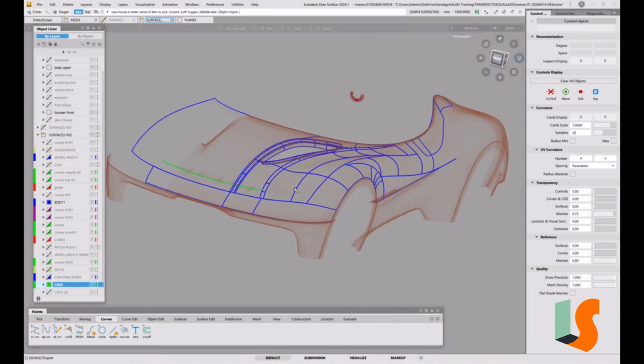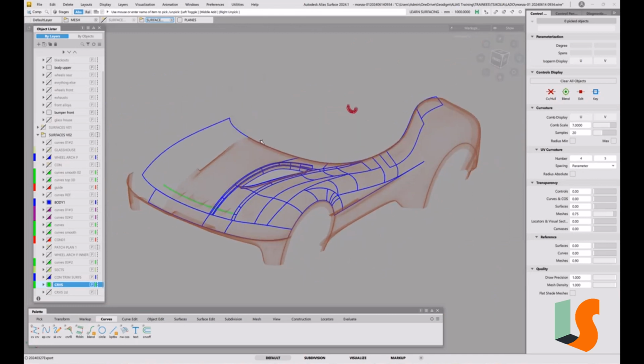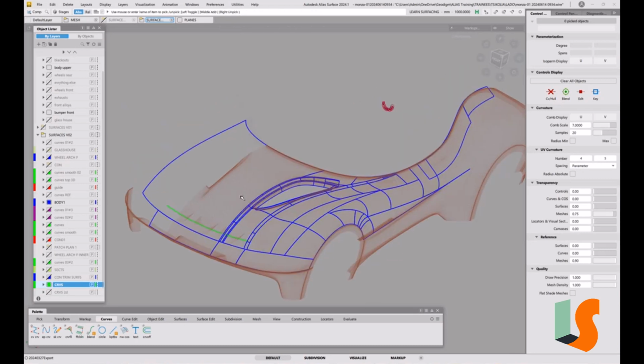Now, before we do that, we've built surfaces across the center line because that's the quickest way of creating these surfaces. When you come into the little details, it's less critical whether you do it across the center line or not. Once you get onto the fillet detail especially, what you want to do is have a half model and then fillet half and then mirror the whole thing across, rather than filleting all the way along there.